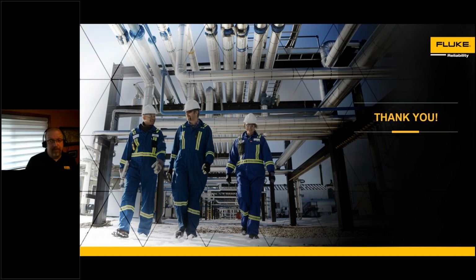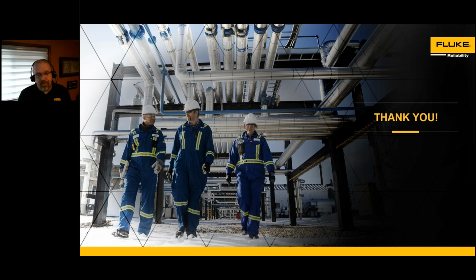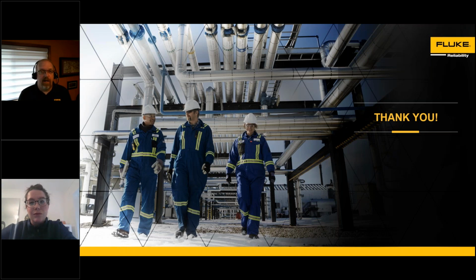That's a great question. So when you're first getting into reliability-centered maintenance, you may see the complexity or the cost as a little daunting. And so the best way to break into it is to explore your options and determine what your critical equipment is, what your less than critical equipment is, and decide for yourselves what you want to monitor first. It may not be in your best interests to go after your most complex thing first, but instead, perhaps your most common or what you're seeing the most failures in. So start with the tiered approach. Start small and work your way up.